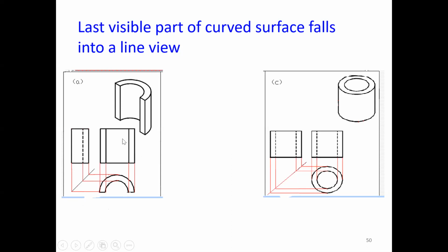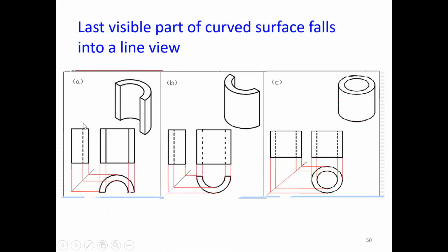Look at here. This one is also. If you see from the front, it is clearly visible, inner hole. So there would be two rectangles at both sides. But if you see from the side, this line is not visible. So that's why for the inner hole, I'm going to take the projection and it is required to show it by hidden line. And if I kept this in a reverse way, so what happened? Both the lines of the inner circle are not visible. So that's why we can take this upward direction and show it by hidden line.